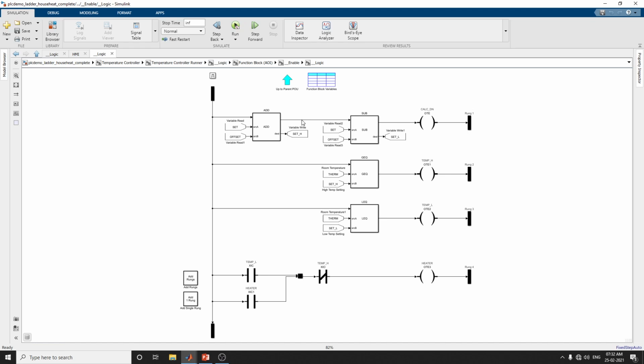Now, as already discussed, what are the rungs it contains? What is a rung in a ladder logic diagram? The horizontal lines in a ladder diagram are called rungs. Each one represents a unique parallel circuit branch between the poles of the power supply. Typically, wires in control systems are marked with numbers or letters for identification. Here you can see the function variables, which you can set directly.